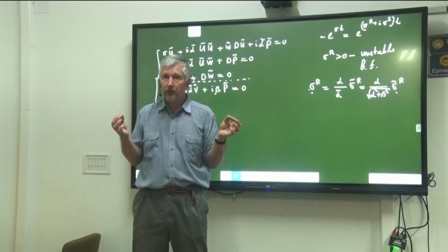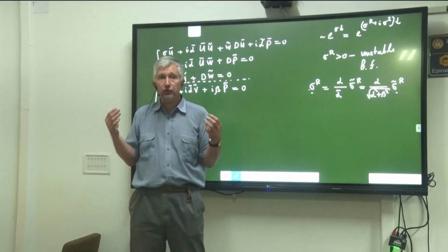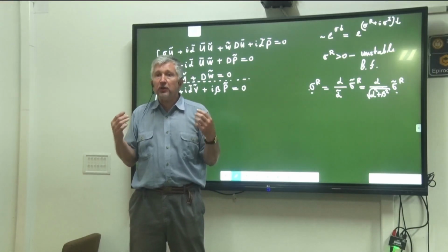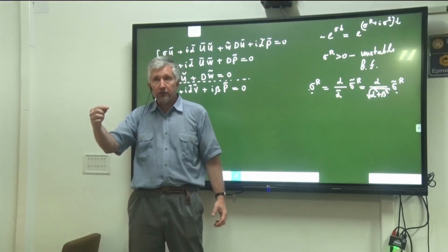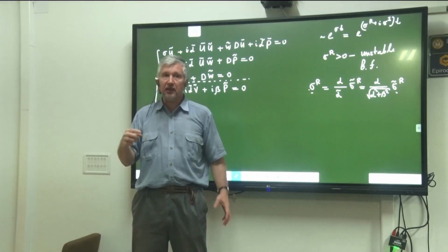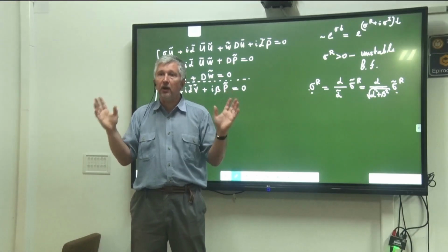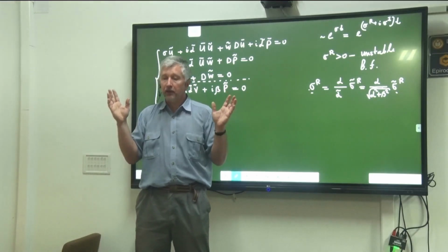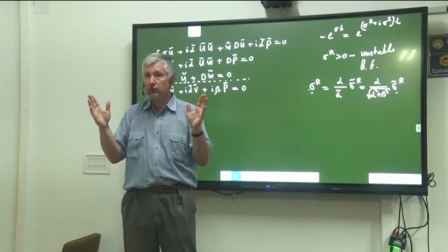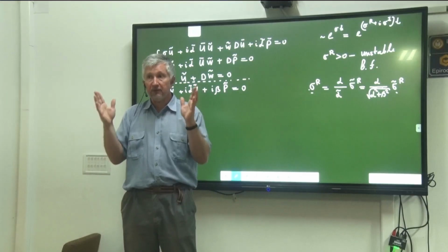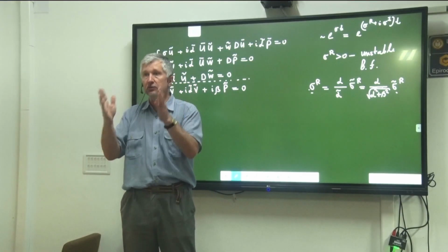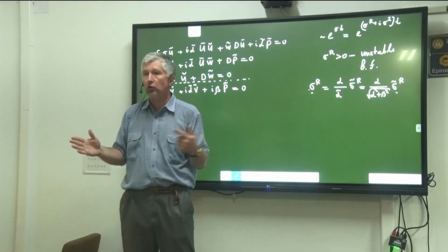It means that if the base flow we choose indeed is unstable, the modifications will occur in the direction of the main flow, but not across. And that means that at any point in time, we will be okay by considering the two-dimensional problem from start to finish. Because we know if anything bad happens to the base flow, this will happen in its own direction, not across.